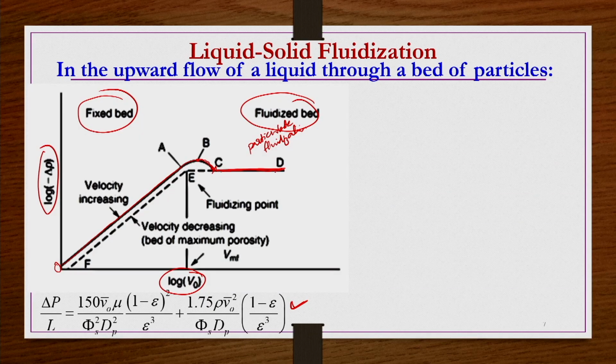Right. So, when you attain the particulate fluidization conditions and find that the pressure drop is independent of the velocity, you then decrease the velocity again, gradually. When you decrease it, the curve goes back from C to D, and from C it is not going to follow the BA path; rather, it will gradually decrease further up to point C. Why? Because initially we had the compact packing with voidage epsilon. Then we fluidized it by increasing the velocity gradually, right.